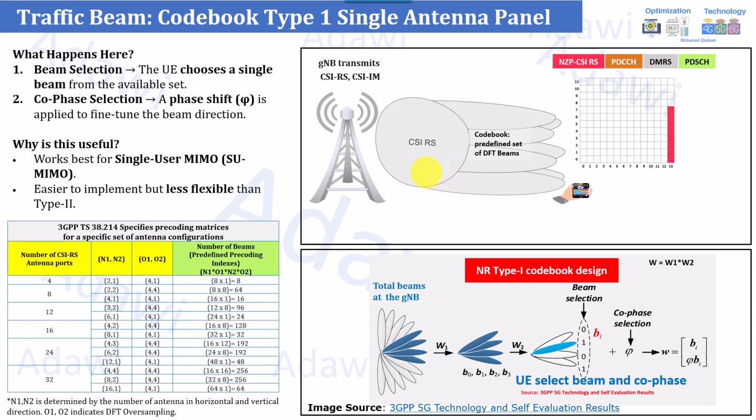So you can configure this CSI-RS resource ID into 4. So this means this one will be 4 wide beams. Okay. So here, all of these, the gray ones, are the predefined code matrices, where the user needs to start measuring the CSI-RS, as you can see here in the right figure.